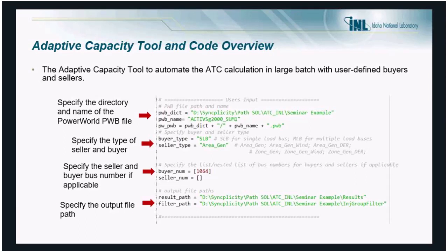Because I don't have the demo to show you live, it's actually a pretty fast process because it's a linearized approximation. It only requires the power flow analysis for the base case, and for the contingencies, it's a linearized approximation. So it's a fairly fast process compared to the 5-bus example, where you have to play around with power flow and eventually see if you have any elements being overloaded. So that's a general overview of the PowerWorld ATC with an example.